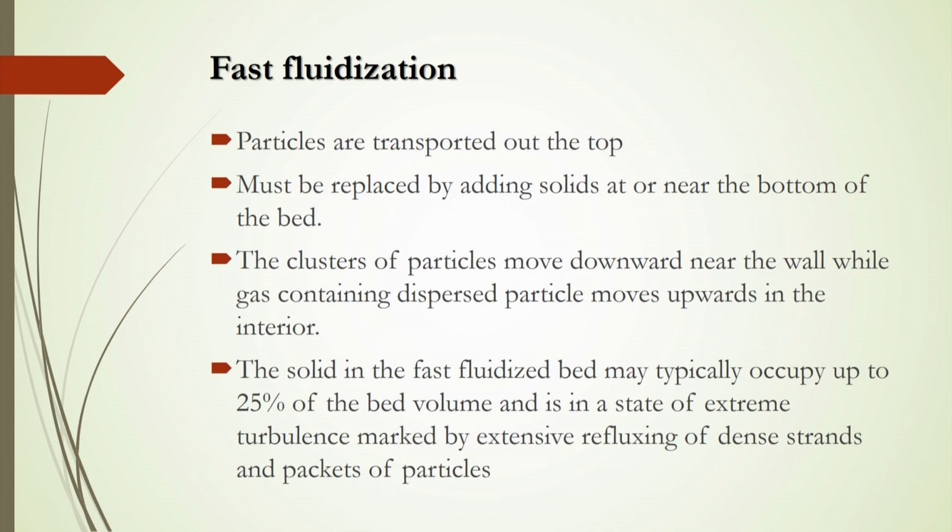And the clusters of the particles move downward near the wall, while gas containing dispersed particles moves upward in the interior. If you are using very fine particles, there will be a chance to form clusters, or you can say agglomeration, and different sizes of clusters will be there inside the bed. That depends on the gas velocity and also the wetness of the solid particles there.